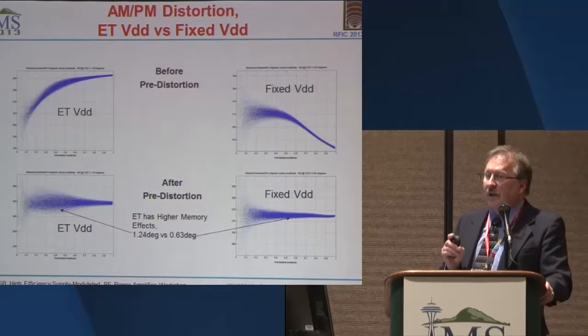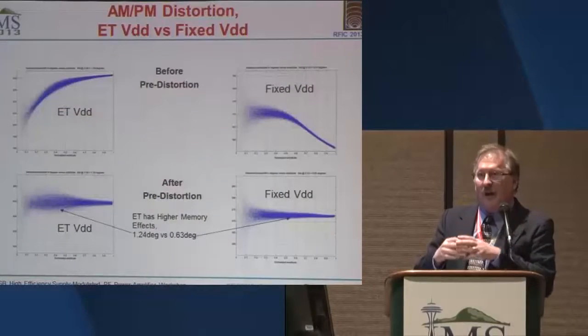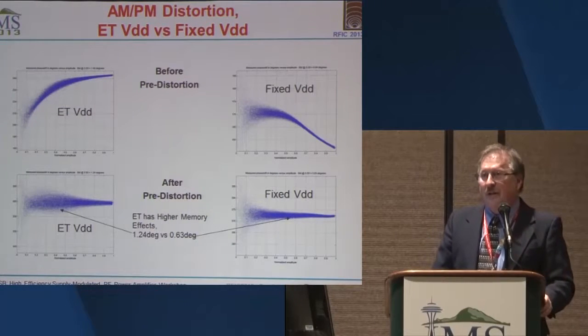I look at this in a complex space. In fact, typically I look at the gain in the complex IQ space, which is a strange way to look at it because most people don't even imagine it that way. And it turns out you can see this splatter much more effectively when you put it into that complex space. The points up at compression are all clustered around a small area, and the same number of points down at the low end cover this huge area on that complex gain plane.